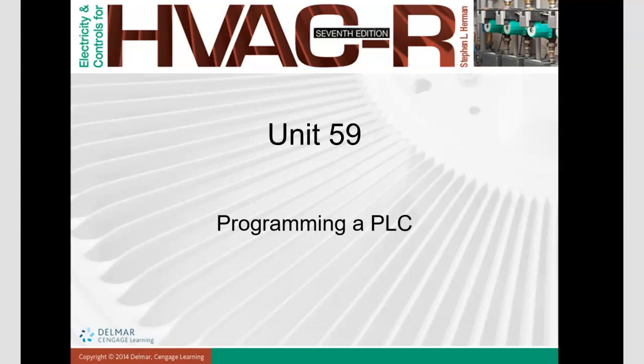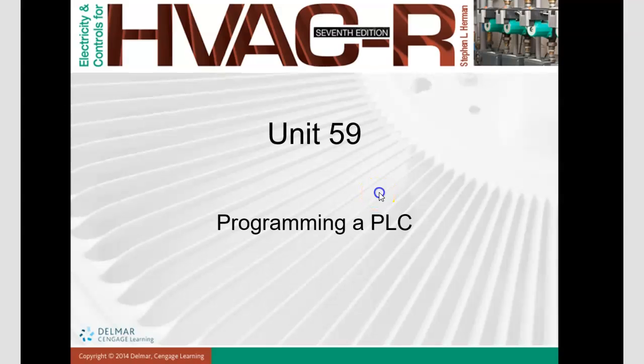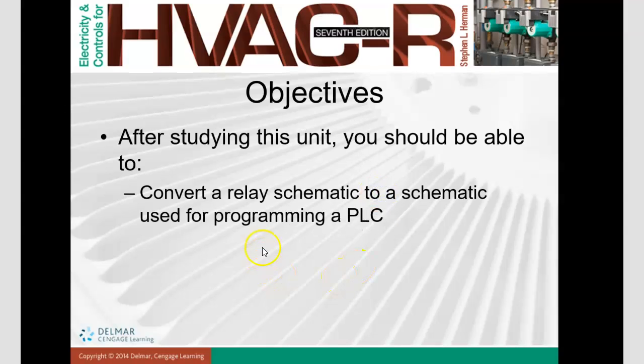Today will be the last topic regarding this one. It is actually not programming of PLC, but how we convert a schematic circuit to a prepared circuit for PLC. That's the purpose of this topic: convert a relay schematic to a schematic used for programming a PLC.